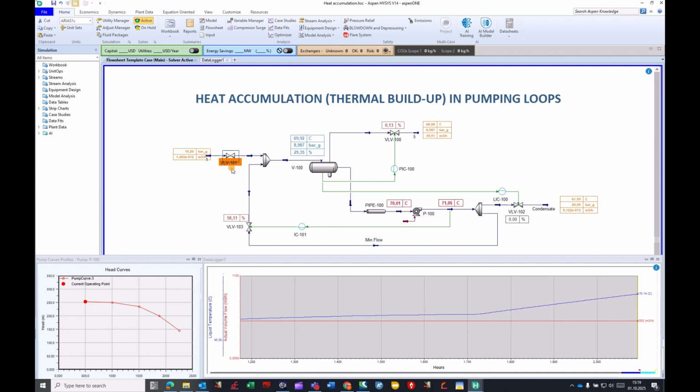If that is in place, then it can help improve the situation and mitigate the risk. But as a primary protection, it is wise to have, as mentioned before, a high temperature alarm and high temperature trip level to protect the system against this situation.